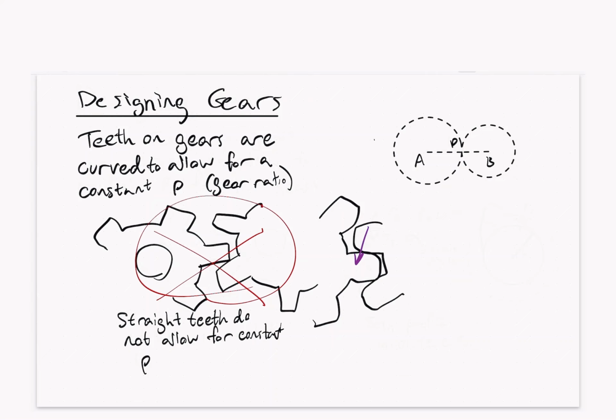So we're going to have a force that's operating down, some force that's transitional, some force that's normal, and they operate at the pressure angle alpha. And in order for that to happen, we need to use what's called an involute curve. So we would say that our base angle would be what we would use to draw that.